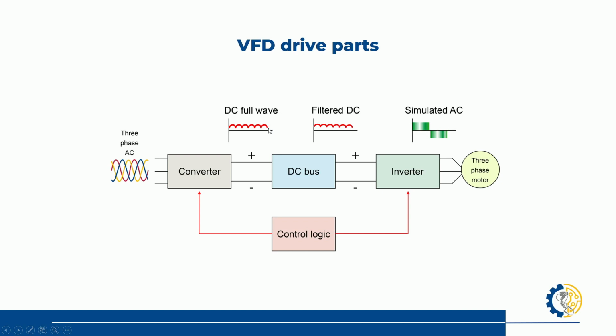So this is filtered, and this is what looks mostly like a line. Once we have this filtered, we are going to be able to command all of our half waves, but by pulse. And with those pulses we are going to be able to simulate anything that has to do with AC, alternating current.